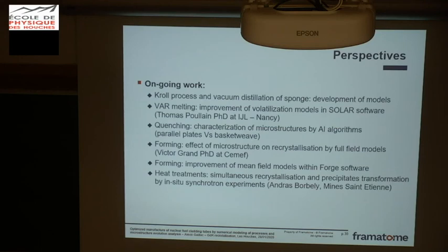And we also have other alloys, because the examples were about Zircaloy-4, which is a quite simple alloy. But we have other alloys where, in fact, after hot extrusion, we have a remaining unstable second phase, beta phase, that will transform later on in